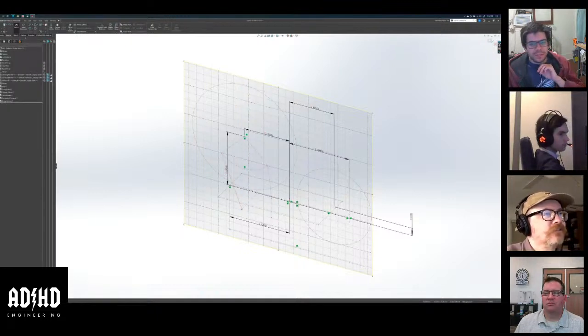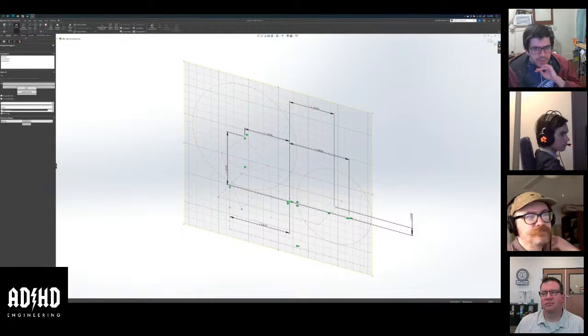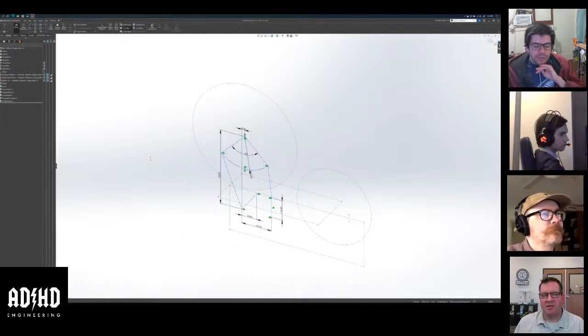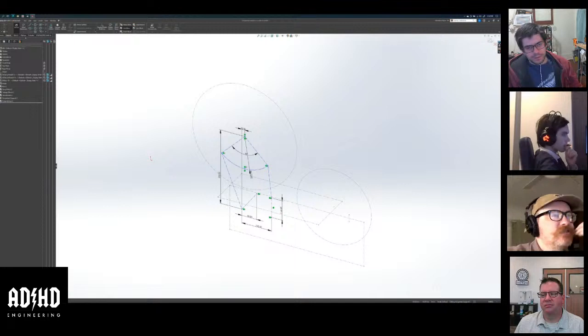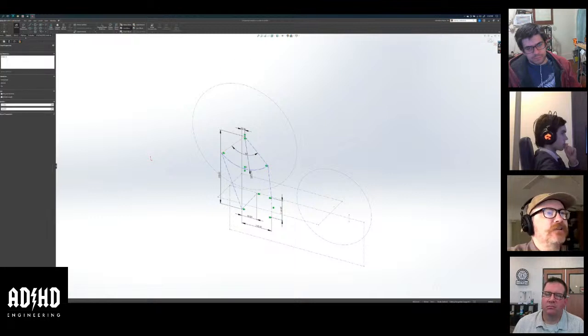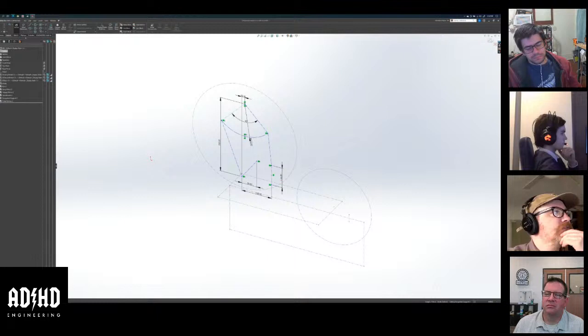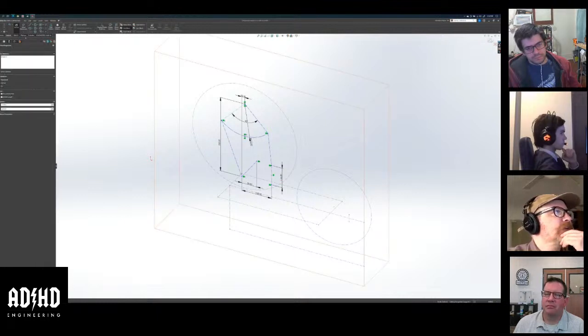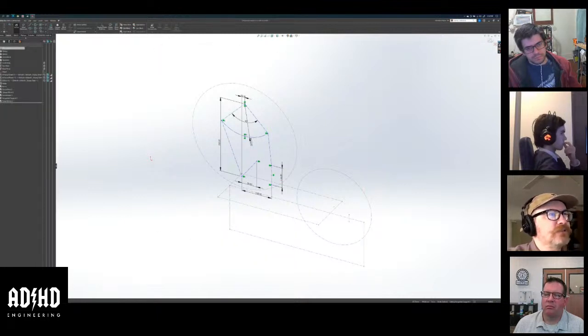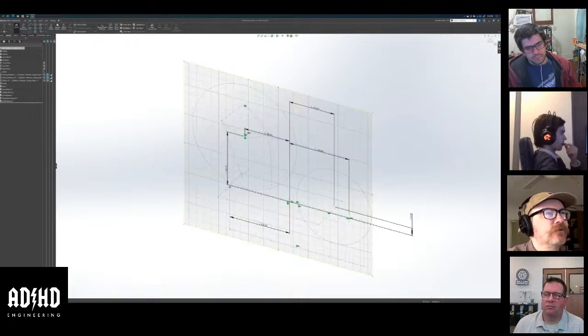Well, okay, this is what I was saying. It's not constrained now. Yeah, you just put an angle of 0 and lock the angle on the block. But he did that already. But now he has to constrain it inside the block, right? Inside the sketch. As a block, it doesn't matter. I could put it wherever I want. But when I finish with the block, it'll orient to where I told it to be in the layout. So if I click edit block, it'll just go back to where it's supposed to be. But it didn't, though. What the hell?